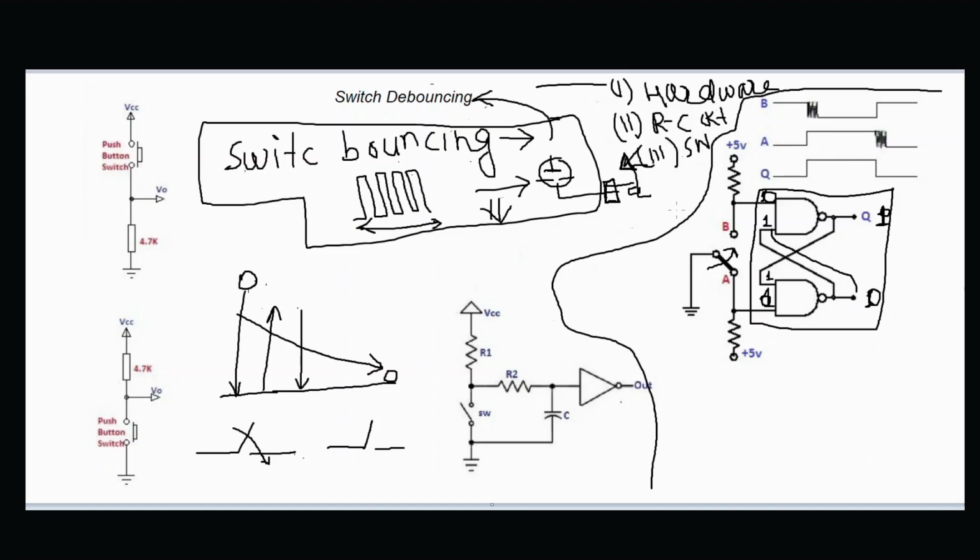So this is hardware debouncing, and this is a common circuit used for it. One of the disadvantages is that this is a bulky circuit. You are using an SR NAND latch, and then there is an SPDT relay which is costlier. That is why it is not used most in circuits.